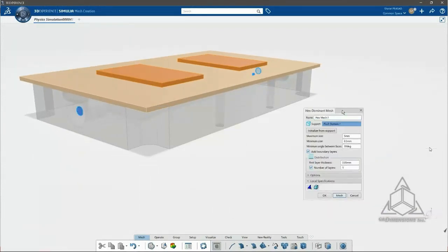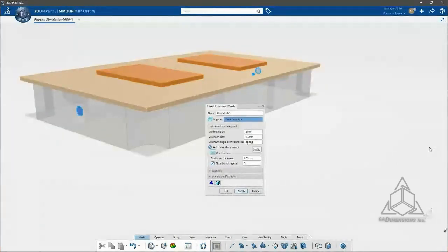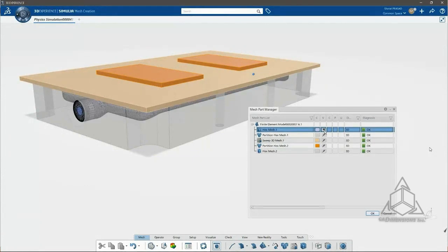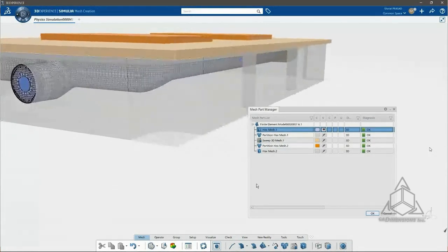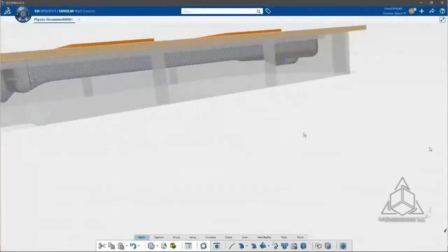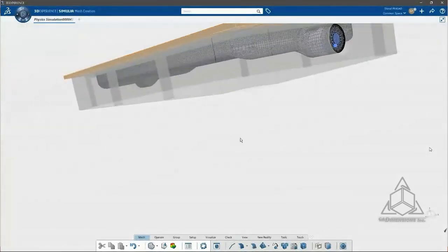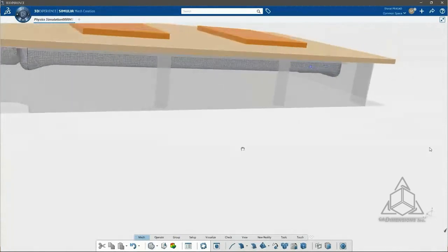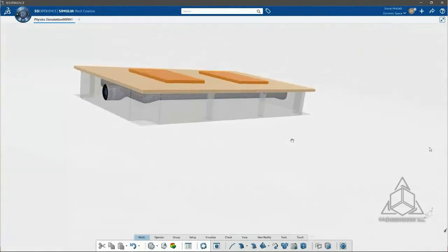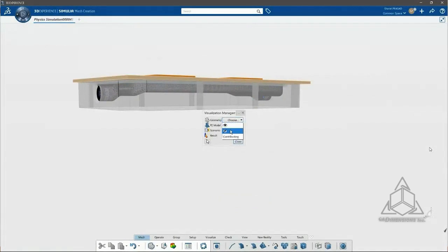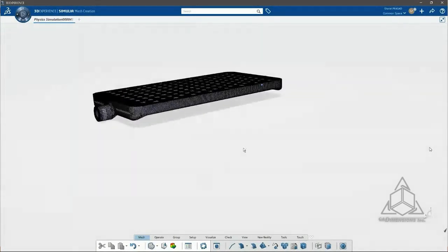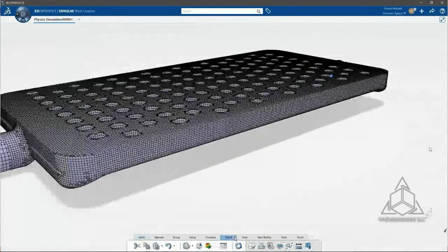The first one is our fluid domain, which is our hex mesh. So we can go ahead and turn that on so we can actually see it. That's our fluid domain number 1, which we can see is kind of our inlet and outlet, our cooling analysis. We can go ahead and see that it takes the shape of that abstract. And once we do a section cut here, we'll be able to see it a little bit clearer. So we turned off all of our geometry. We can see it wraps around all those capacitors.